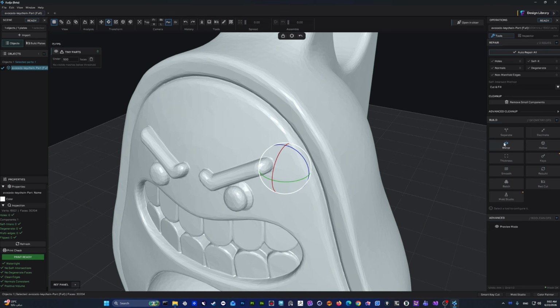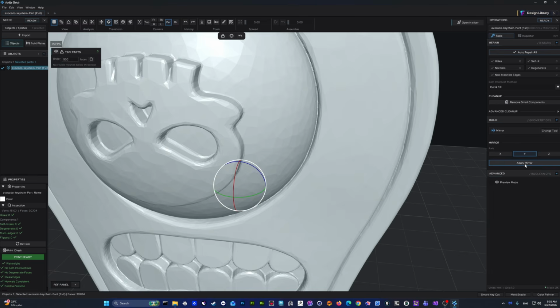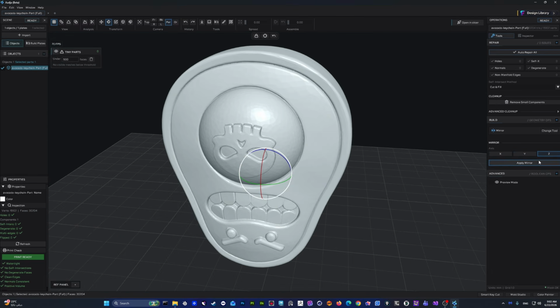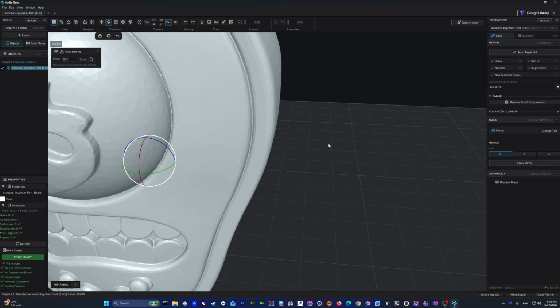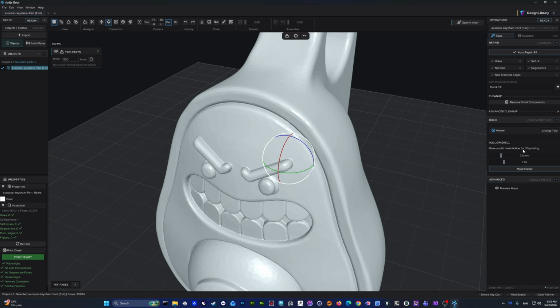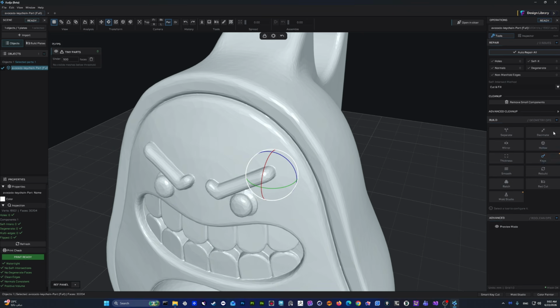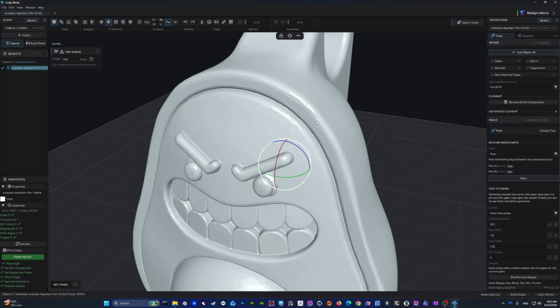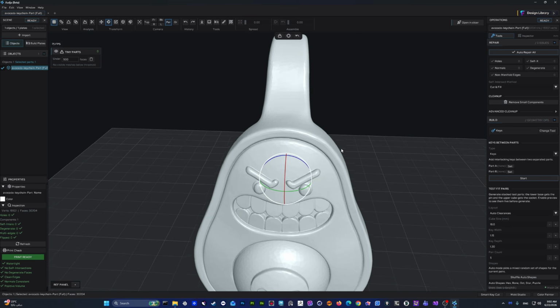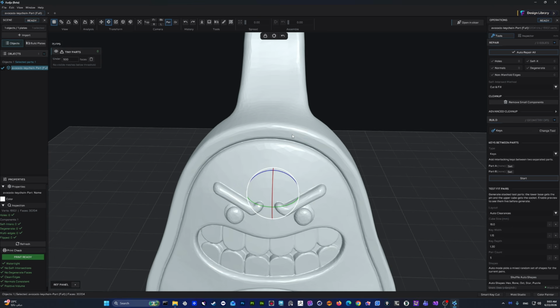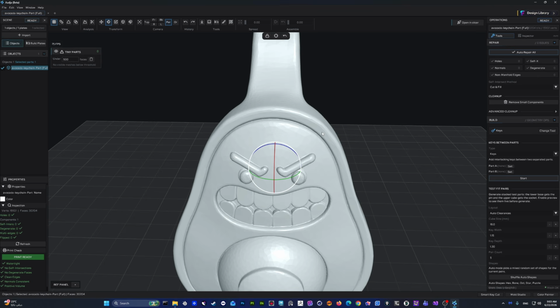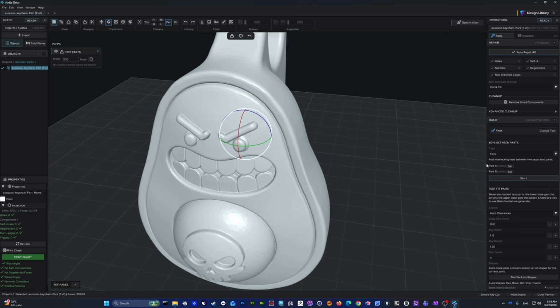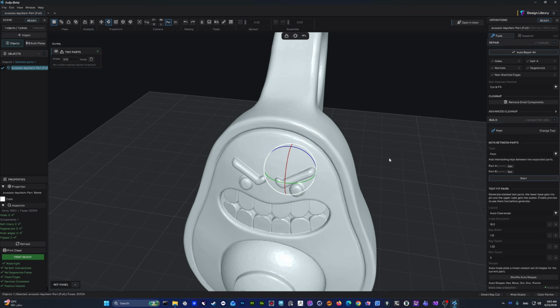Okay, and we have mirror, and this one, you know, it's making left right and right left and upside down if you don't want to use any gizmo or anything for this. And we have the hollow here. I'm gonna explain it more in another video. And the thickness also, keys, that's if you want to make joints or connectors between separated parts, already separated, and you want to make keys between them, but one by one, not automatic. So you're gonna set part A and part B and start. I'm gonna also explain that more.